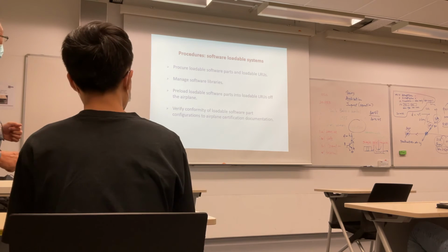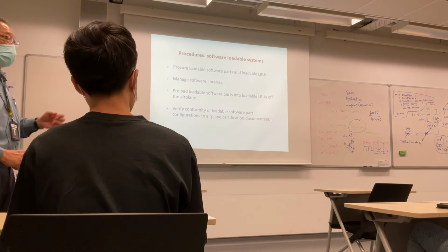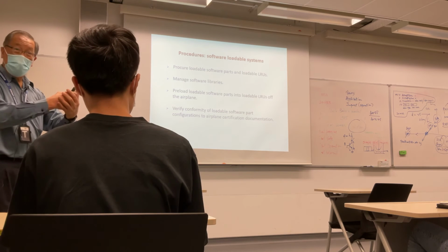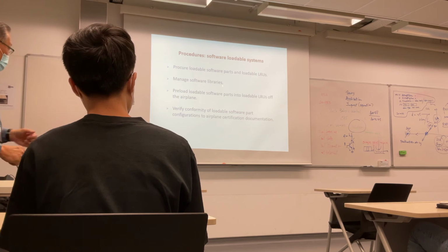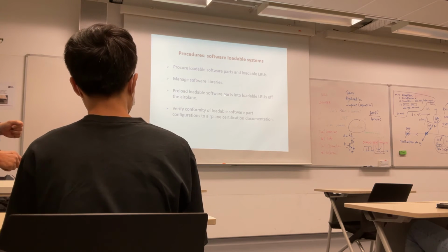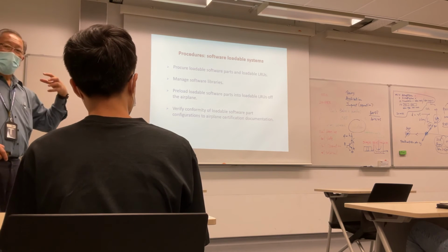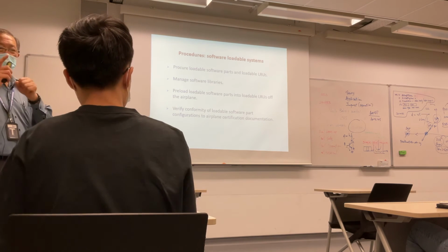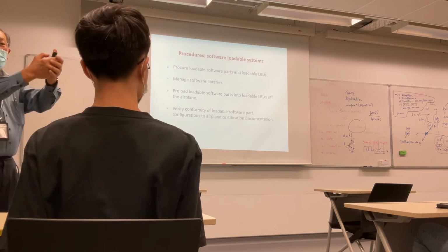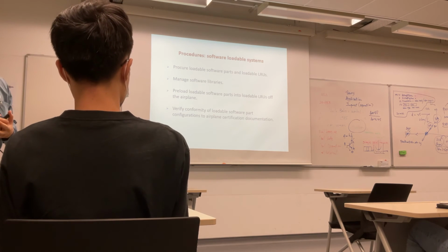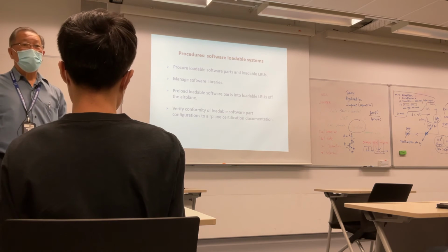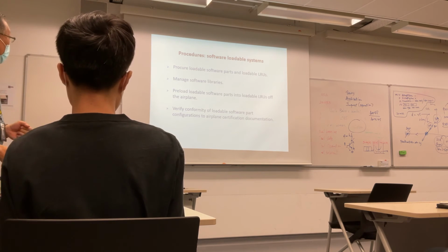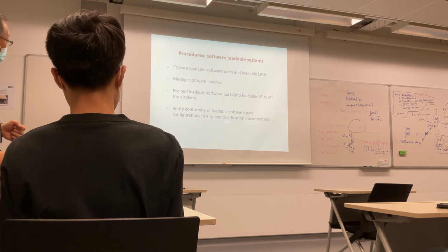So the procedure here is loadable software. That means when you buy it, there's a process to check it before you can put it on the aircraft. Somebody has to certify it, like you manage libraries. Preload software, loadable LRU, that's very important. Sometimes you preload outside of that, meaning you don't let the LRU do it, you put it in a shop and load the whole LRU inside the store. That means you have to buy more LRUs, which is not a good idea. In a large fleet, it can be very significant. Then verify conformity again.